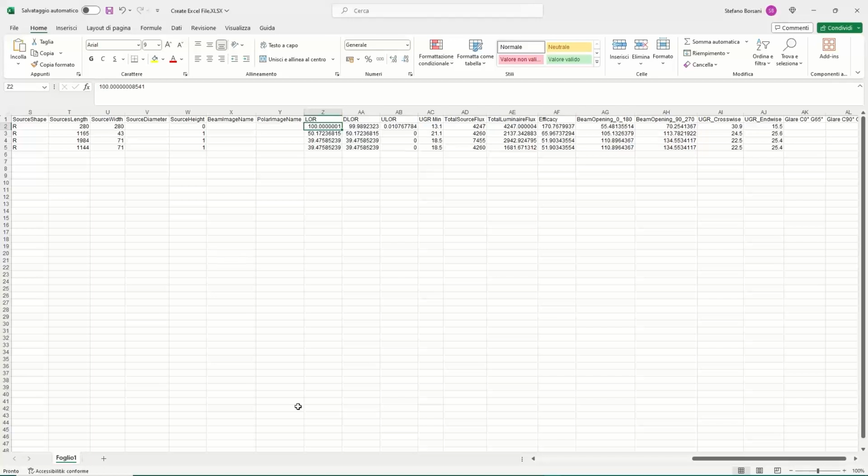to the created files. So for example, if you change the flux of your luminaires, as we said before, because you are using a new LED generation, so you have to change the flux. But if you want to keep the efficiency at 100%, so you want to consider absolute photometry, then you have to fix the 100% value here, so that the program will automatically modify the matrix in order to give at the end the same efficiency.